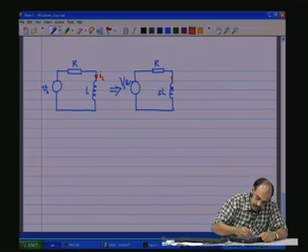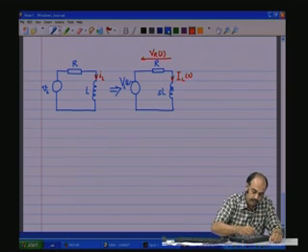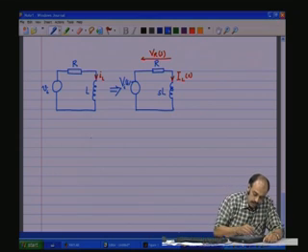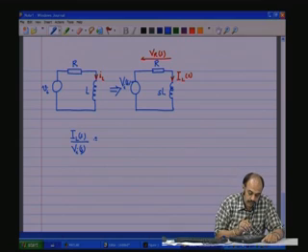And we have IL S as another variable here, and if you want to have the voltage across R, it is VR S. All in the Laplace domain, you will have the Laplace variable which is the S variable coming into the picture. So, now if you want to have a transfer function of IL as the output with respect to the input VIS, what do you get?